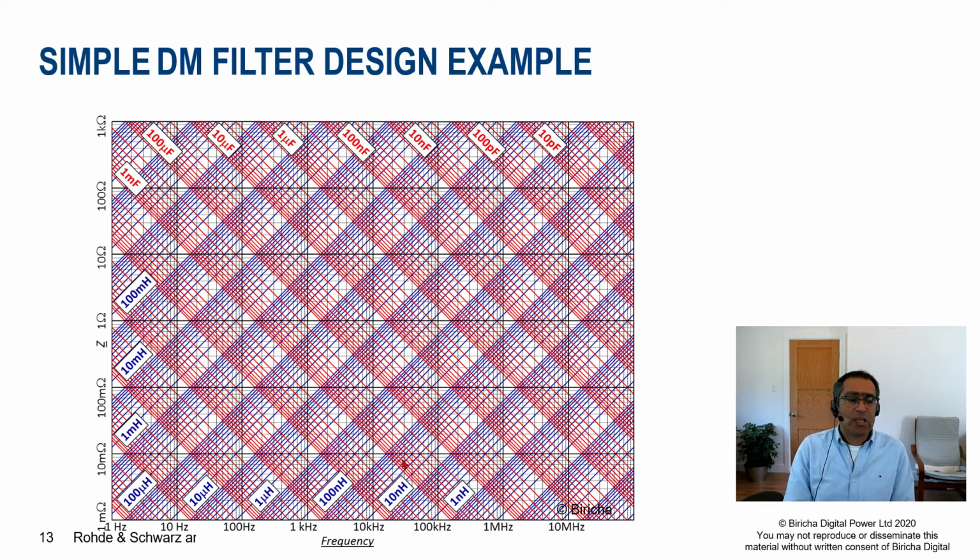Let's say that we have calculated that our cutoff frequency for our filter, in order to pass whatever standard, has to be 10 kilohertz. Actually, we're going to give you an equation for that very shortly. But for now, let us say the cutoff frequency of our filter is 10 kilohertz. So there we go, there we draw the line.